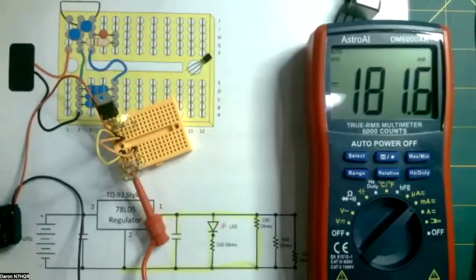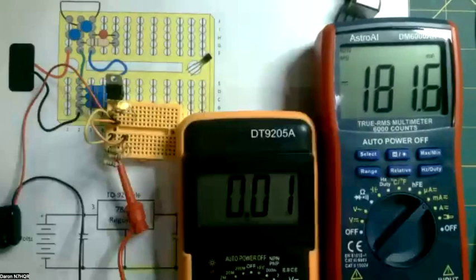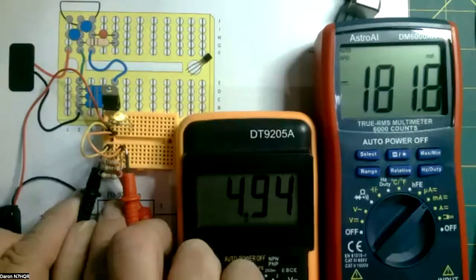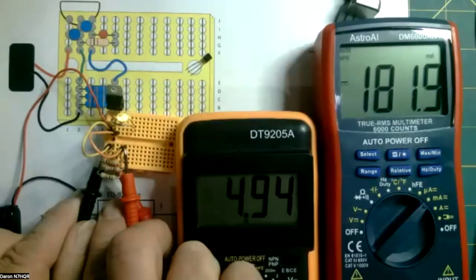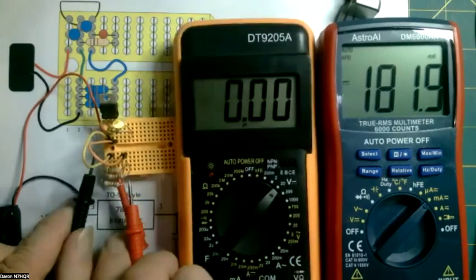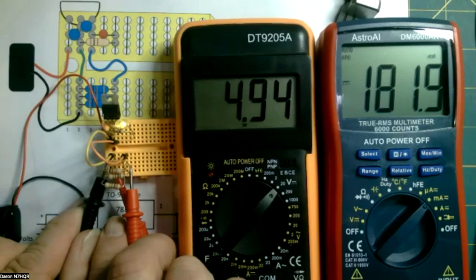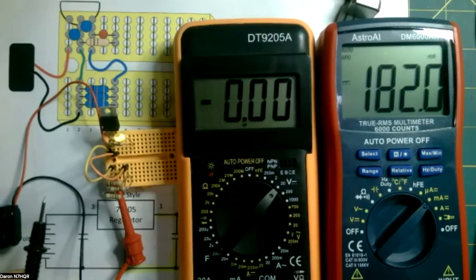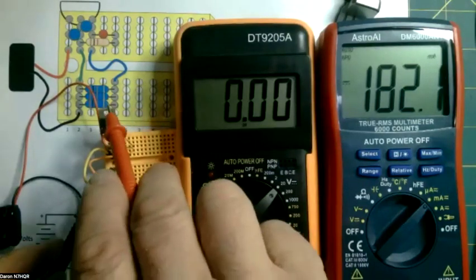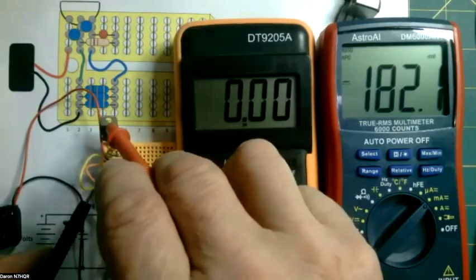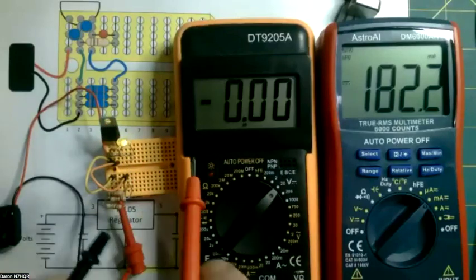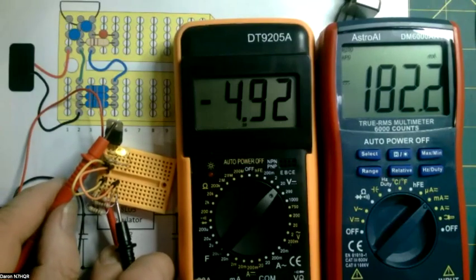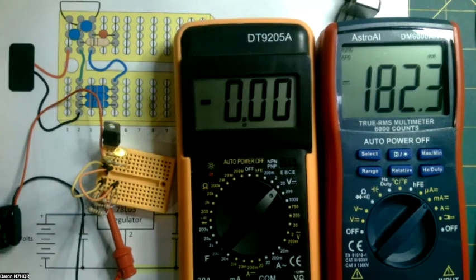Do they require a heat sink to operate at their rated current level? Which one? Well, either one of them, actually. The first one, no. It does not require a heatsink. The second one, yes. You can see the metal tab on there. It needs to have a heatsink on it if you're going to run a full amp through it. And is the tab the output? Or is the tab ground? No, I think it's ground. I believe it is. On a variable regulator, the tab is the opposite, I think.